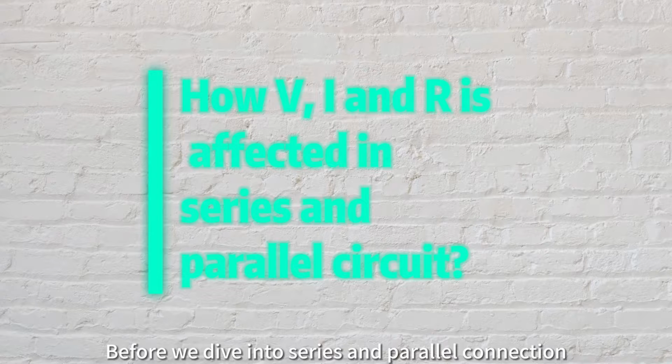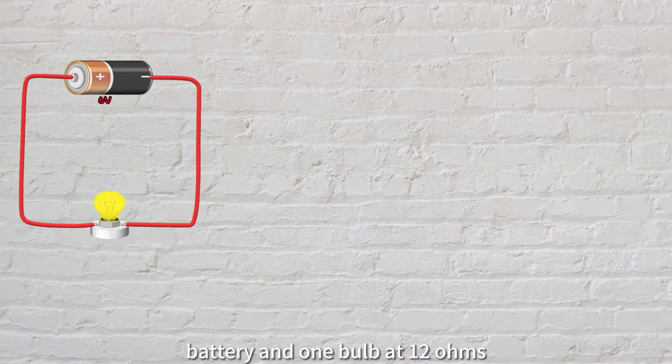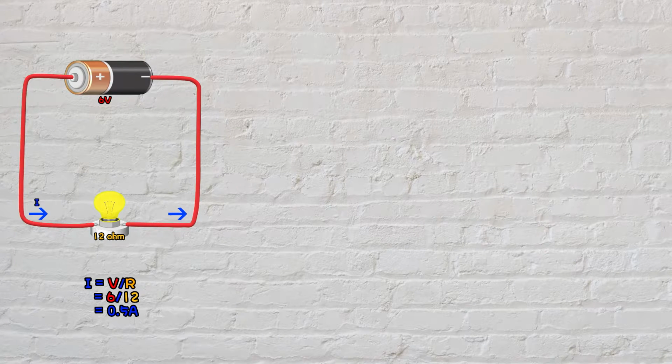Before we dive into series and parallel connection, let's look at a simple circuit with a 6 volts battery and one bulb at 12 ohms. Using Ohm's law, we can easily calculate the current to be 0.5 amps.